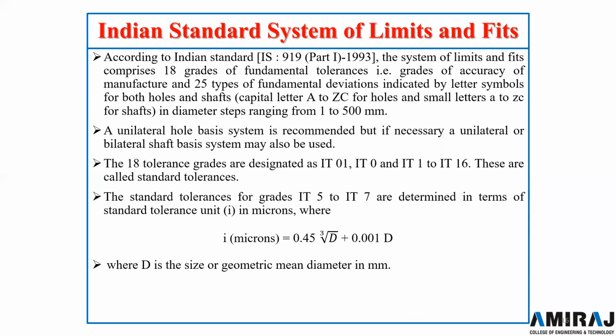So remember this. The first thing you need to remember is that the unilateral hole basis system is always recommended from the manufacturing point of view, but sometimes if it is necessary that a unilateral or bilateral shaft basis system is needed, then we can also use that.